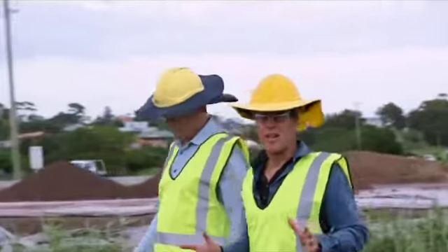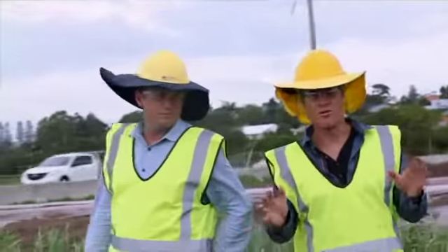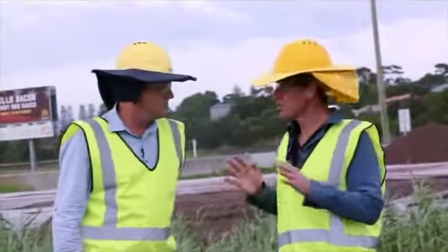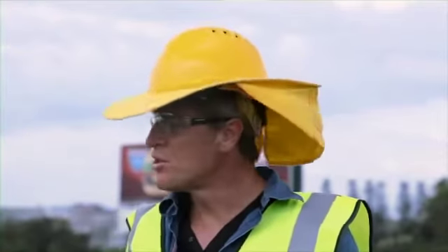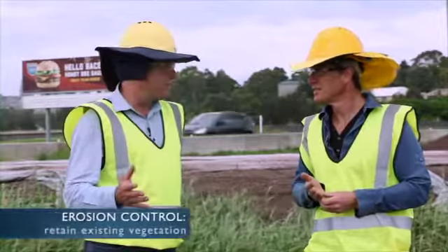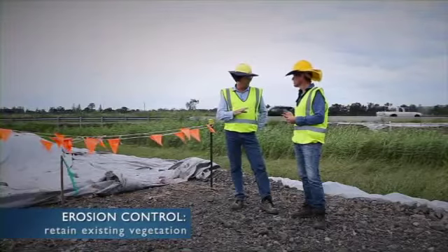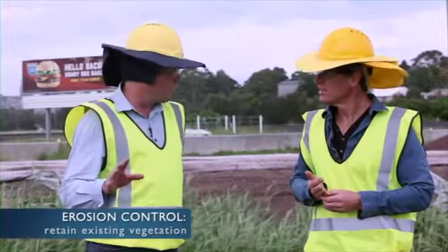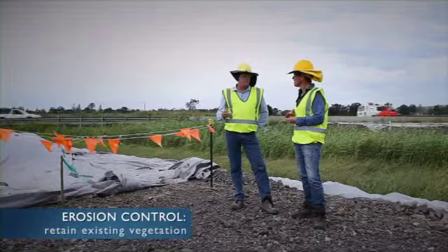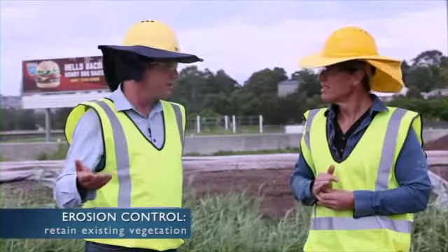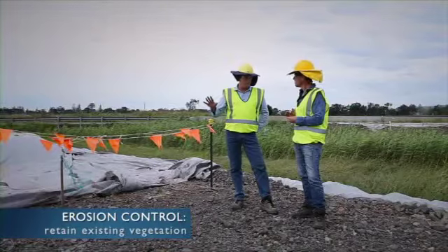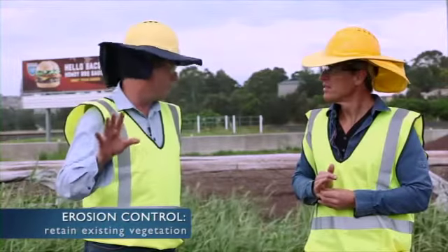So we've isolated the upstream water around or through the site and isolated the construction zones. So we need to protect those exposed areas of the site with erosion controls. Yeah, we've got a number of different techniques. We've got natural techniques. We can retain vegetation where we can. We can also use mulch and other natural controls. There's a series of products we can also use, like geotextile fabrics, plastics, etc. And what we're really trying to do is protect that exposed soil from that erosion process.